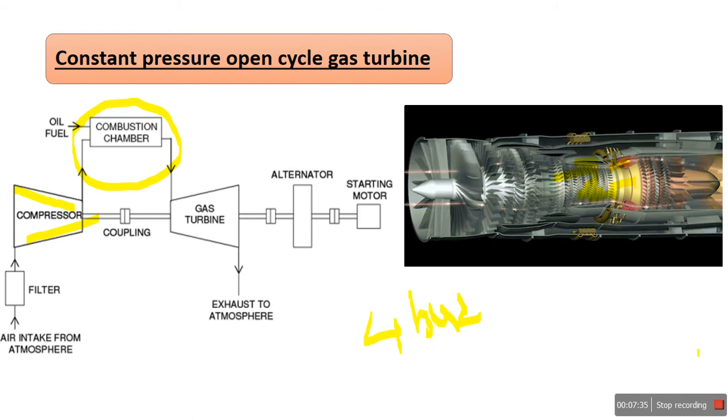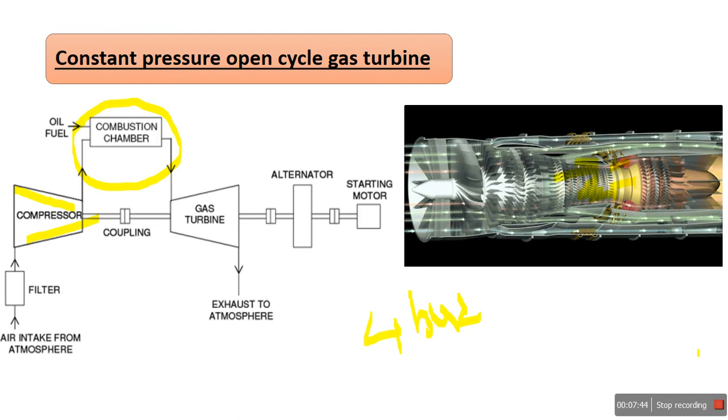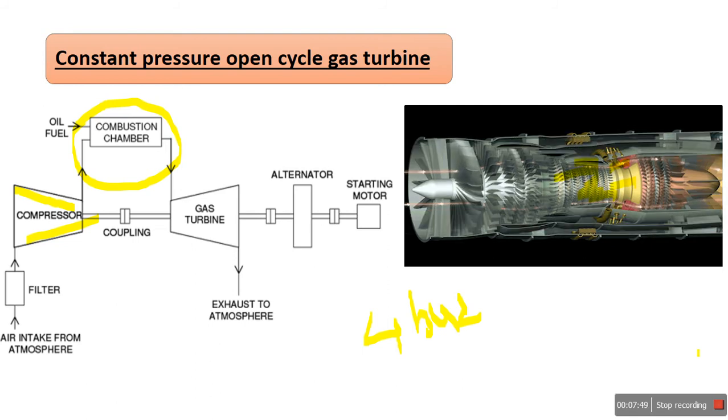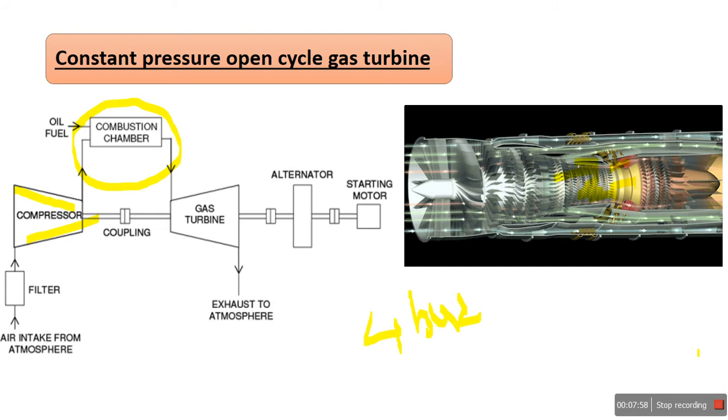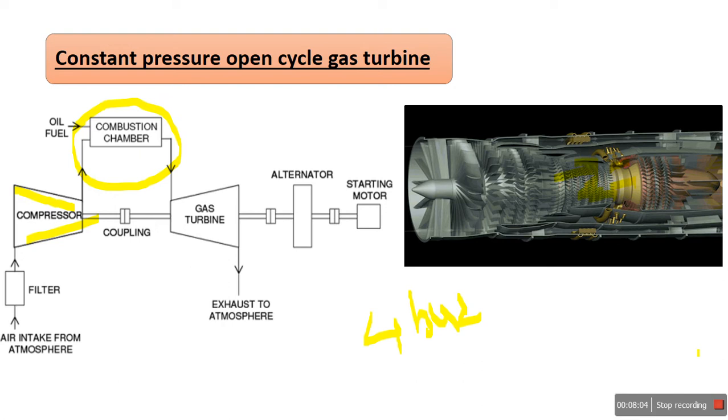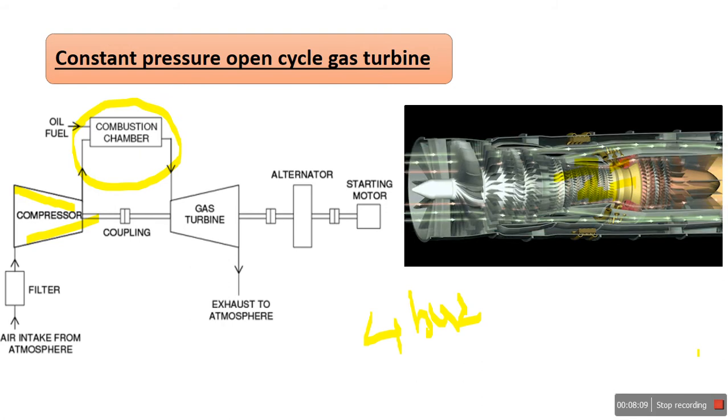Otherwise, because of some material considerations, the temperature in the combustion chamber would go to 2000 degrees Celsius. Because of material considerations, we have to maintain the temperature at 600 to 800 degrees Celsius, which is possible because the combustion chamber is provided with an annular casing. Finally the gases are exhausted to the atmosphere. The combustion gases, before exhaust, flow over the turbine, where we develop power, and the turbine and compressor are mechanically coupled. If you see here, the turbine and the compressor are mechanically coupled.